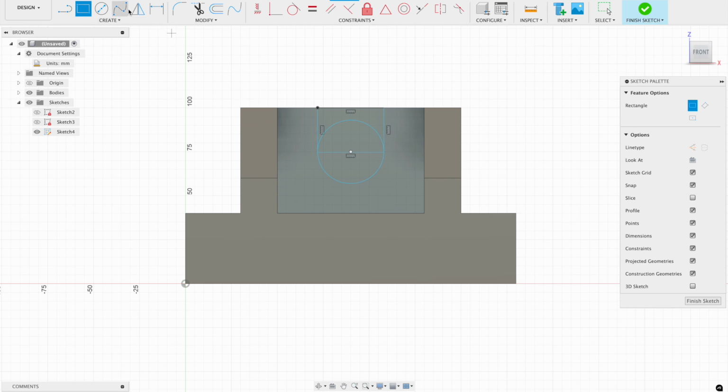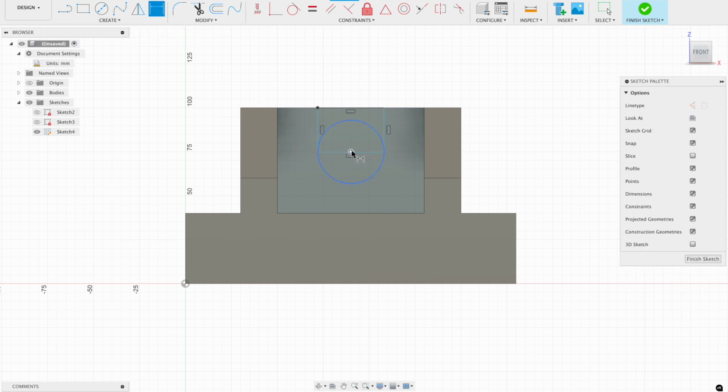So that makes it very easy for us. We'll start with our diameter, say that's 40 units, and then from top to bottom, it's 20. Okay, and then if we're going from the center, again, we figured out earlier that this entire length is 80, so from this side to this side is 40. Okay, now our circle is fully constrained.